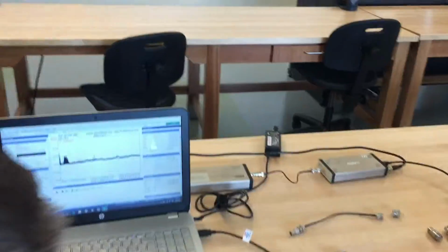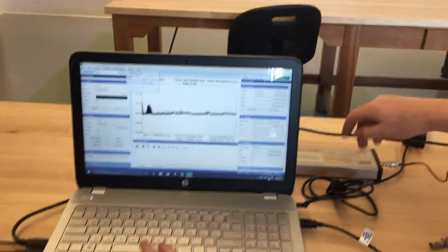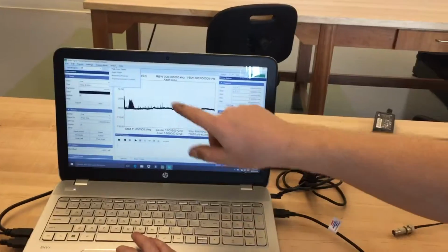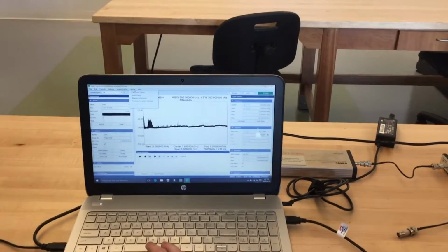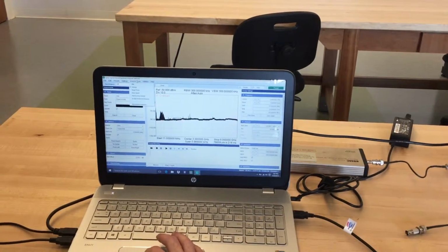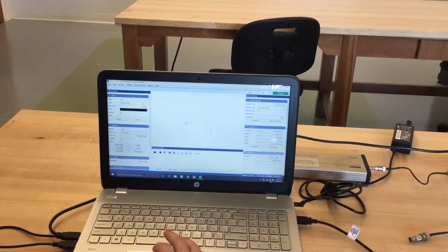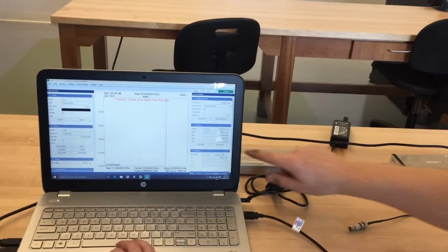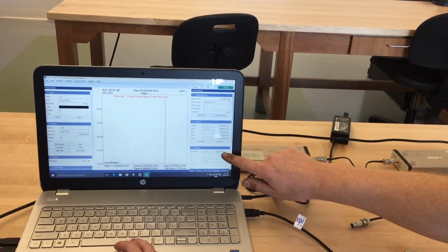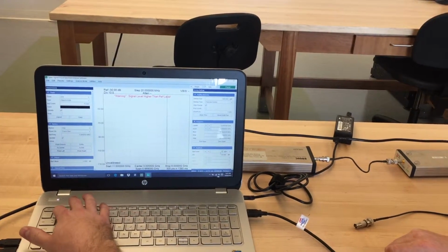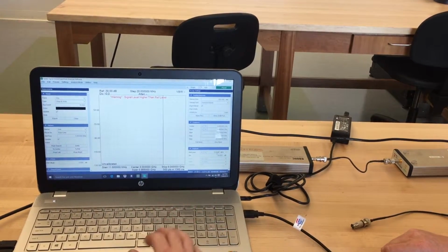Okay, Rob, will you go up to the utilities menu? This is the software. This shows us the graph of what the signal generator is receiving. It doesn't really mean anything at the moment. Could you go to analysis mode? One pull down menu over. Good. Go down to scalar network analysis. Good man. Now, could you go down here to the 10 decibel level? Make that 10, not 30. The reference level. Good. Just hit 1, 0 and enter. It'll know what to do.